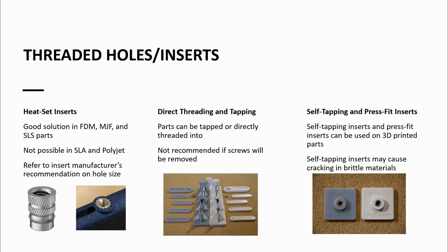For threaded holes and threaded inserts, this choice depends a lot on whether the fastener will be repeatedly screwed in and removed or will be inserted once. If the fastener is only going to be assembled once, then direct threading and tapping may be a good choice. However, if the screws or the fasteners will be removed repeatedly through the threaded hole, we recommend using inserts such as heat set inserts, self-tapping, or press fit inserts.